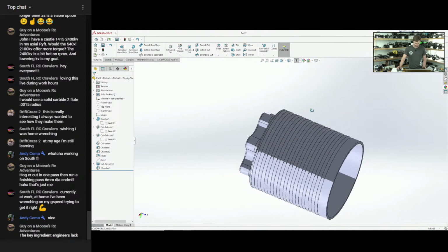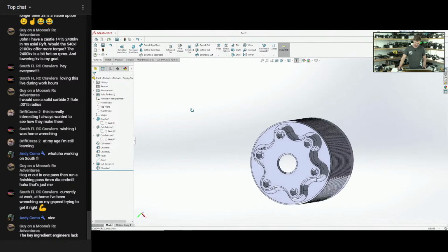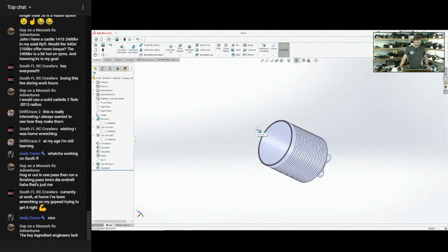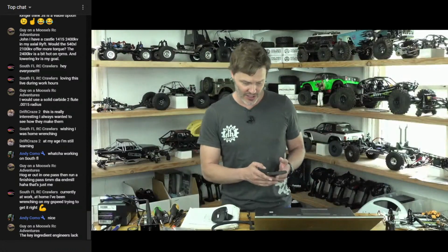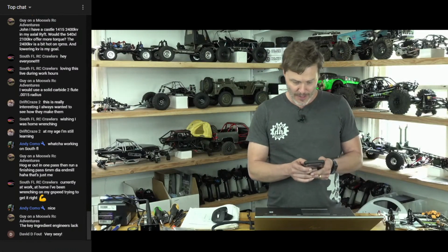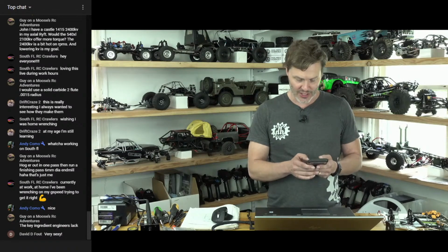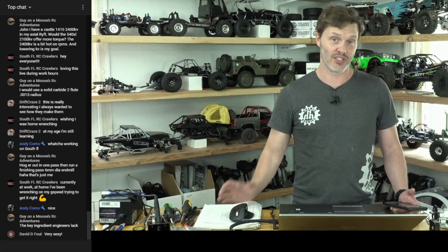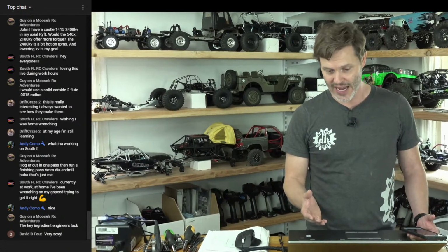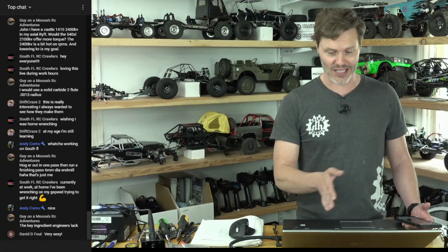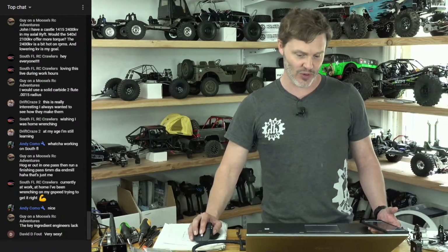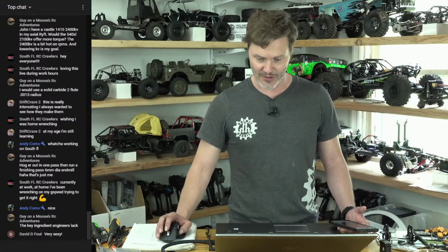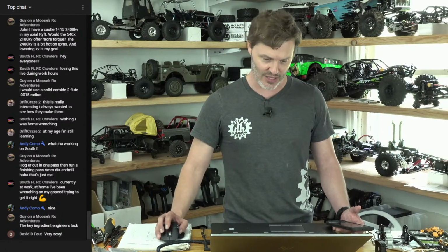To get into the rest of the nitty-gritty, I'm going to have to do an actual assembly, which maybe we can do a fake motor assembly in the future. Or maybe a 3D printed item as well. I know that most of y'all are going to have 3D printers. That's more of what you're into. But this was a revolved object. This is something that's going to be CNC machined on a turning center, so it's going to have a lathe that gets in for all these operations, and then we would have the milling operations on the side that get in there.